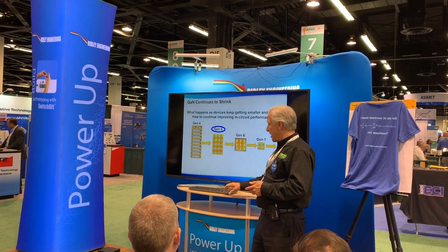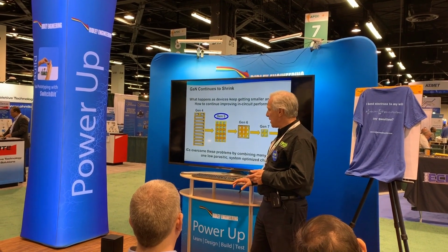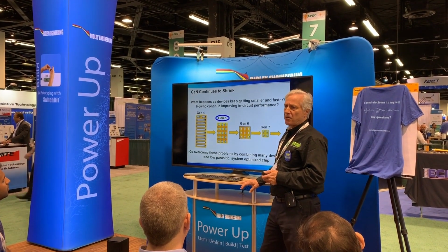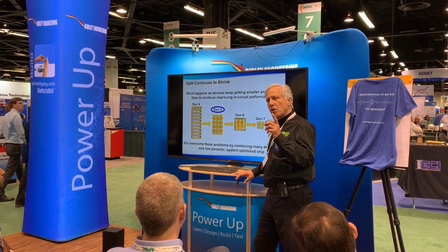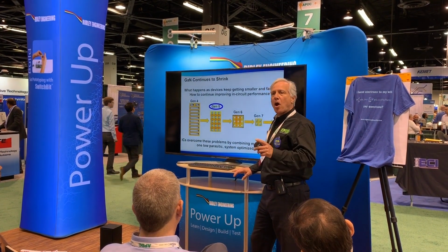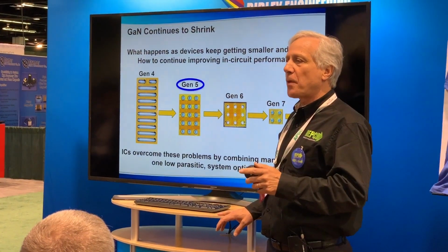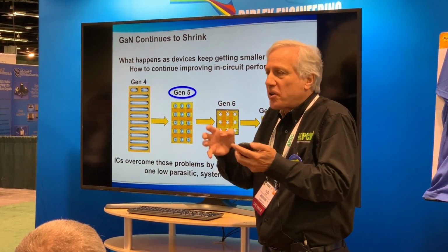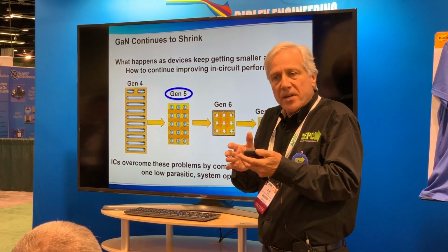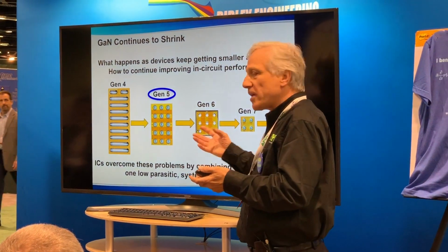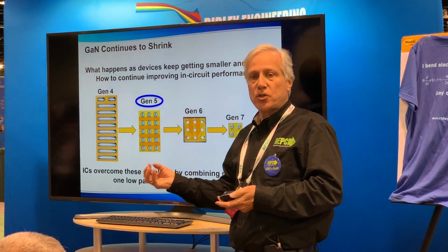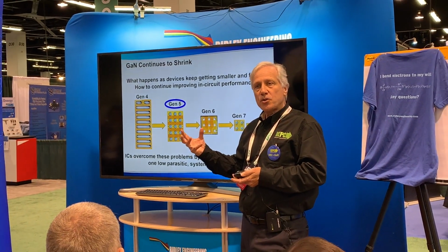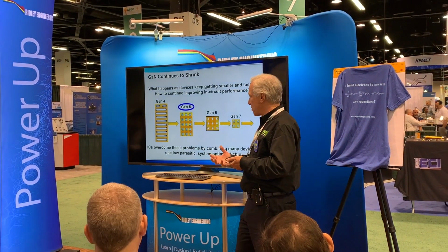And then we're starting to get into limitations of how to get the current out of the bumps themselves. So this becomes a very different problem. In digital logic, you have the problem of how do you make your line width smaller, because then your transistors are smaller and you squeeze more in there. Well, with us, our problem is that as you get smaller, your current density is going up, but you don't have more room to get your current out. So you got to start doing things to minimize that.